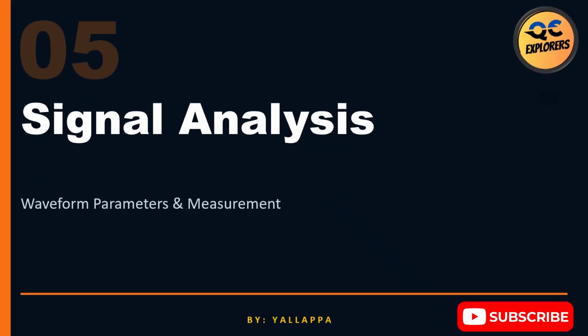Signal analysis is one of the core areas of acoustic emission testing. Every AE waveform contains measurable parameters that help us understand the behavior of the source. These include hits, counts, and amplitude. Analyzing these parameters, inspectors can evaluate source intensity and defect activity. This is where AE becomes both an engineering science and an interpretation skill.